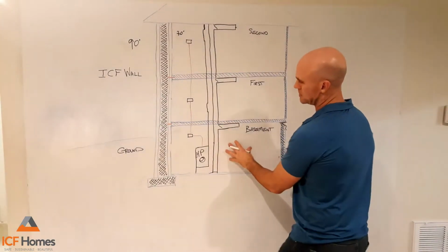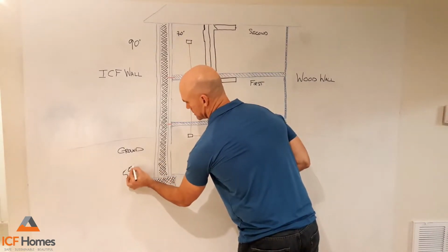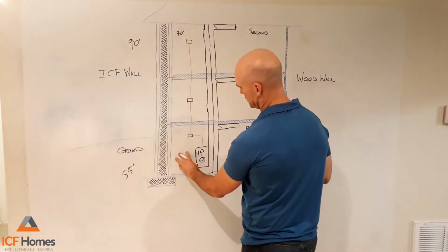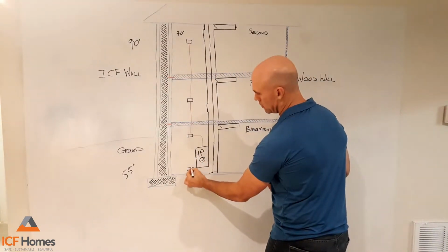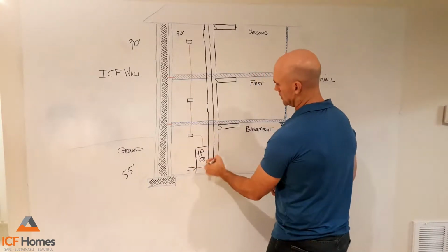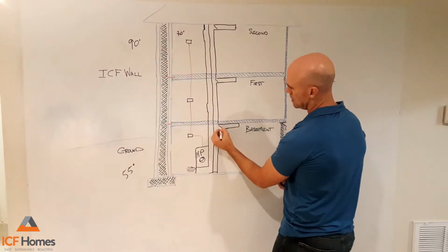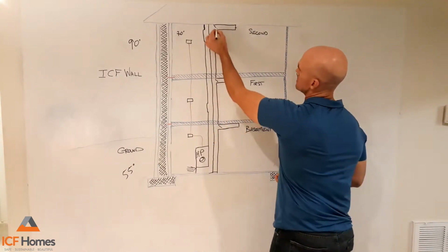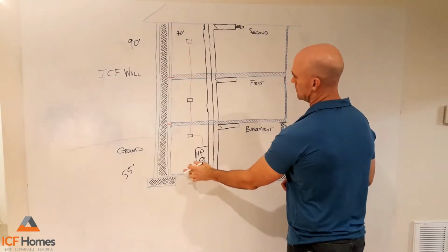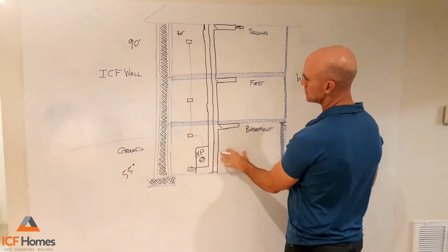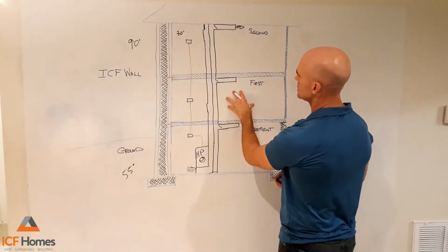But we've got our steady basement temperature, which by use of the steady ground temperature of, we say, 55 degrees, the air from the fan running on the heat pump will pull air in low in the basement, and it'll pull it into the system. And because the basement doesn't need cooling and the first floor doesn't need cooling, the dampers here are closed. This damper up top opens up and it blows out the air from the basement that moved all the way up to the top of the house. It was already nice and cool, and it helped to cool the second floor of the house. If the first floor needs cooling, the same thing happens.